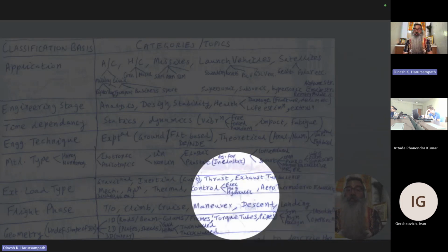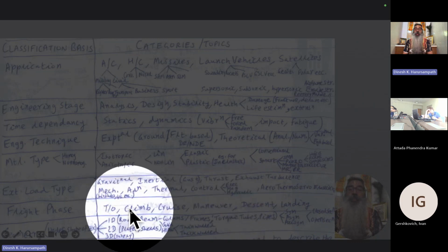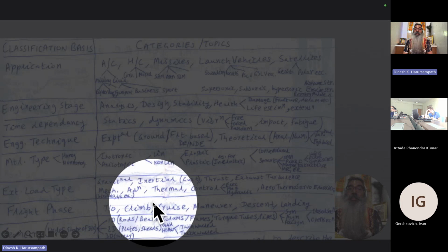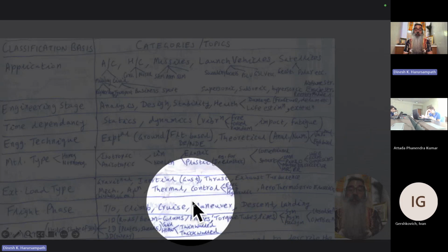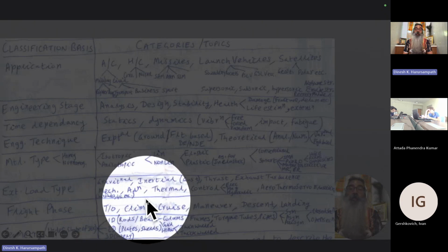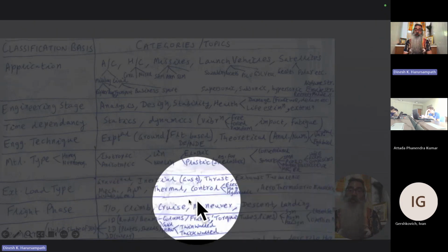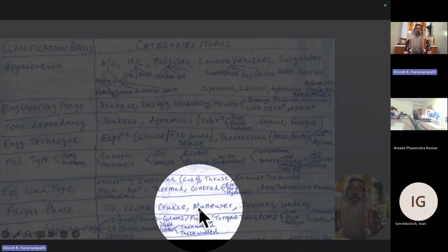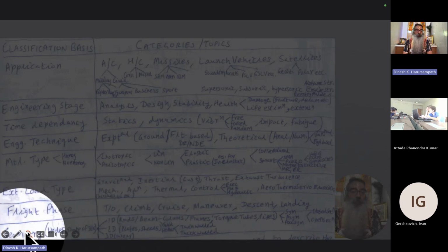But the other things become a little complicated. Which part of the wing is facing which largest load or largest stress or most critical condition under which phase of flight? So that may not be necessarily the maneuver. Some of those could be in takeoff or in climb. So it's important for us to consider all the flight phases and to make sure that the most stringent condition is taken into account for each part of the structure. So that's as far as the flight phase is concerned.